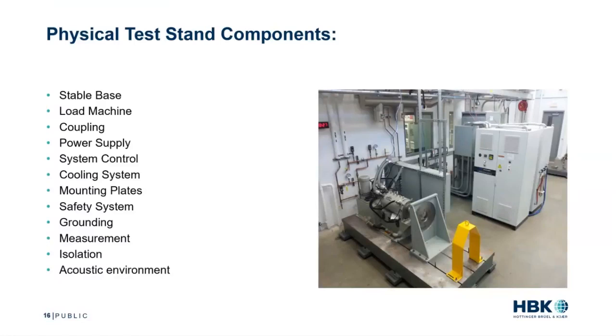So, first and foremost, and it's probably the most boring thing I could talk about, but when we're looking at a torque ripple stand for NVH, especially when we start looking at higher power traction machines, having just a heavy, stable base plate, and I'm talking about this big guy at the bottom here, is infinitely important, because that's going to really give us a stable grounding, so that the machine's not jumping, so that we're not getting outside effects. Basically, we're just putting that resonant frequency of the test stand so high that all our data is going to be really good, and we have confidence that when we're measuring accelerometers, when we're measuring torque ripple, when we're measuring power and efficiency for that matter, our test stand's not moving and jumping around on us. And I think a lot of people take that for granted.